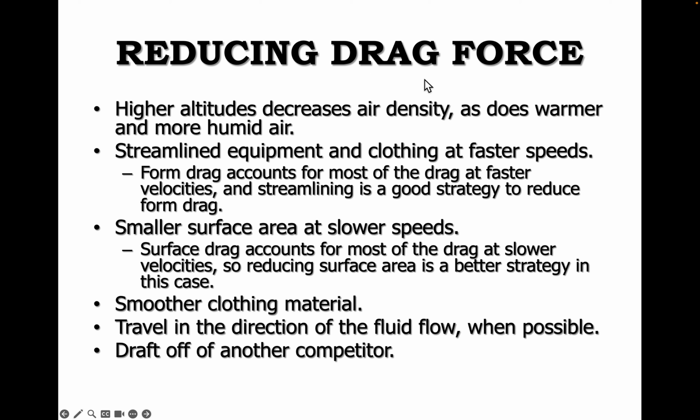So how do we reduce drag force? Number one is go to higher altitudes. Because at higher altitudes, higher above sea level, such as higher up in the mountains, there's less air density up there. So fewer air molecules in the air. And because of that, air density decreases, which means objects can travel through the air much more easily. Also, warmer air and more humid air will also decrease air density. So warmer air, more humid air, and higher altitudes will all reduce drag force.